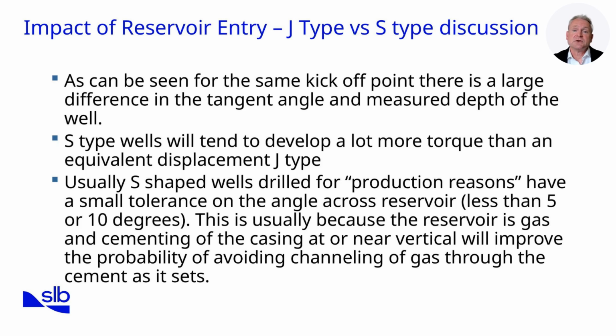S-type wells introduce a drop after the tangent. This creates an S trajectory, often used for gas reservoirs where zonal isolation during cementing is critical. Approaching the reservoir more vertically allows cement to cover the annulus more uniformly, reducing the risk of gas channeling.